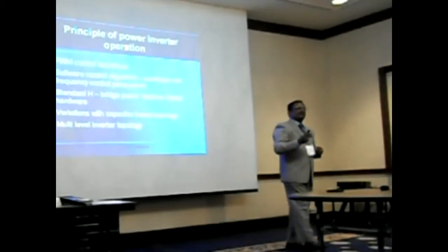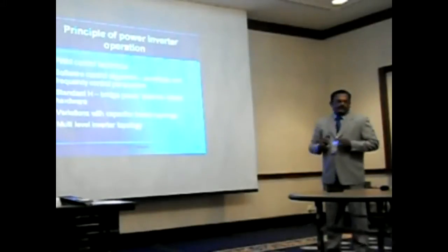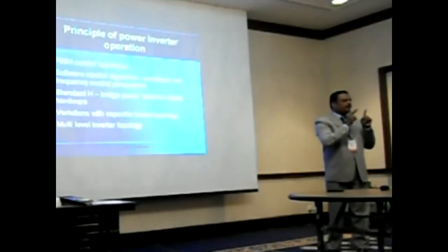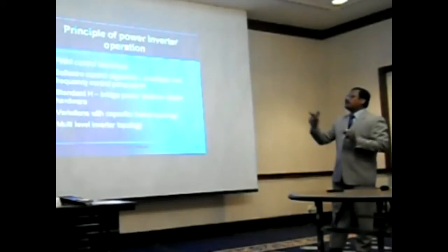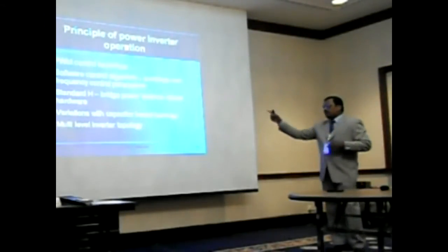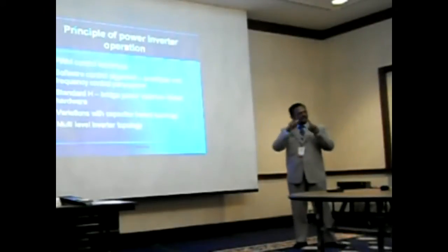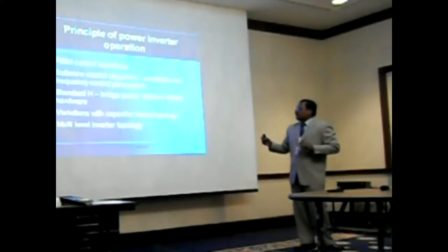The methodology used for generation of this sine wave output is the pulse width modulation control technique, where the width of each pulse that is driving the power switches is changed. Now we have a set of modulation techniques. So the modulation here is that the pulse width is changed. And the complete algorithm is software controlled. The hardware uses an H-bridge, a standard circuit where DC input is given and you take an AC output.